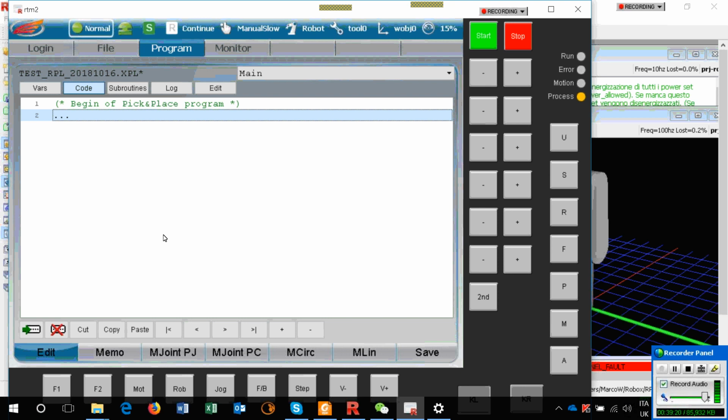Imagine my robot is here. I want to move here. I say move line will make the row, the line. I say move joint, the robot will say I only have to move axis 1. So we make a circumference, an arc, because the easiest way is just to move joint 1 and make this. No need to move this one, okay. But in the row, I make the row, I have to bend this, then to make it large. So, geometry is controlling the robot.